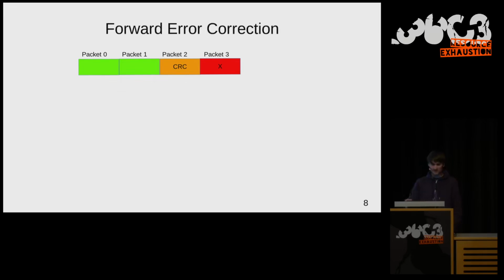Well, simply by adding forward error correction to the data. And the way I implemented it is actually quite straightforward. So to these payload data packets, I simply add forward error correction packets, 2 or more. It's configurable depending on your needs and on your link quality.